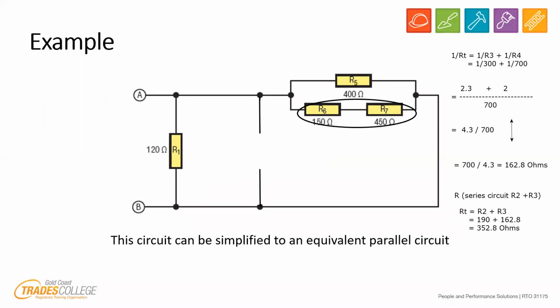And we're just going to do the box, which is there. You can call it what you like. To keep it nice and easy for us, I'm just going to call it R2. The value for R2 is over there, which I'll write in because I will forget, 352.8. So there we go. We've simplified this part down to a single resistor. This single resistor is the same now as R1 in connection, not in size. So that bit's all good.